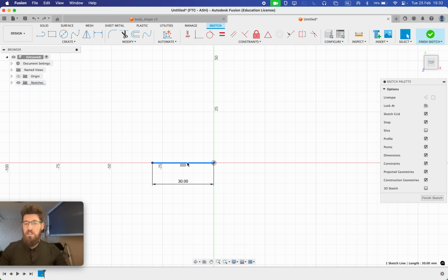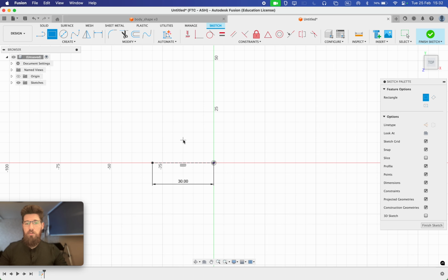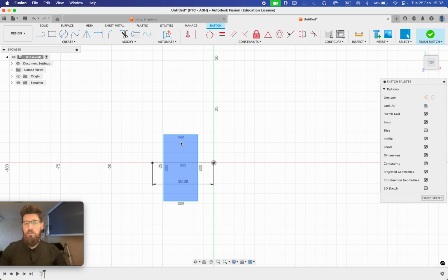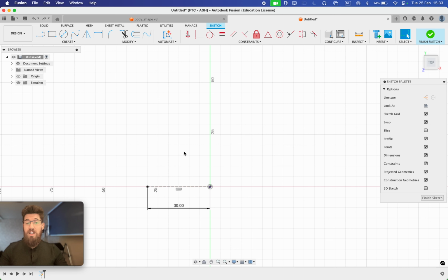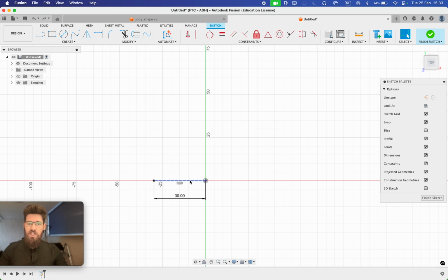So I'm going to go ahead and select the line. On the right-hand side, underneath, I'm going to select construction for my line type. Now, if I were to take a 2-point rectangle and put it inside, you'll notice that it only selects one line, and it doesn't actually split this up into two faces. Because it is a construction line, it's used as sort of a dotted or dashed line as a guide or a template for you, but not actually a line. I'm also going to go ahead and draw my center line at this point.